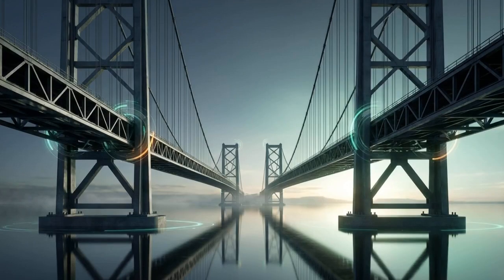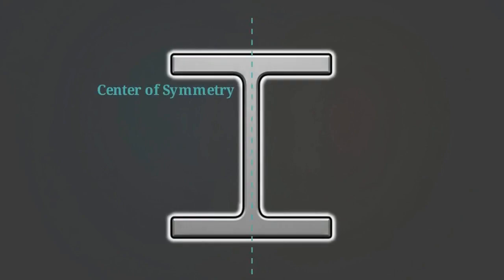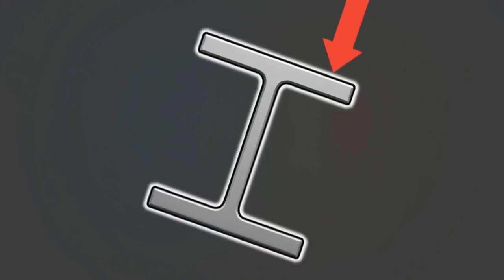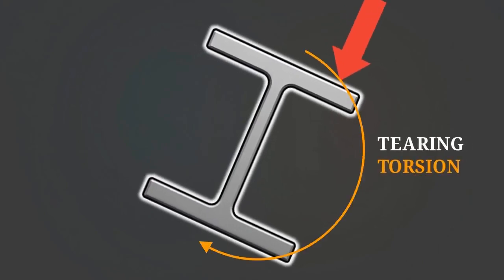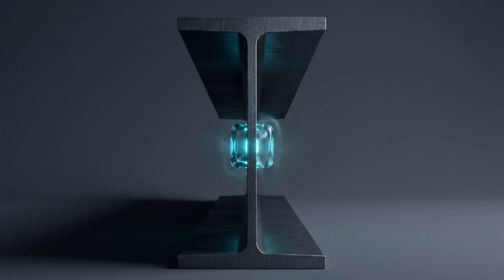But this perfection assumes the load hits the beam exactly on center. If a force lands even slightly off-axis, it introduces a tearing torsion. Finding the single point that can stop that twist requires locating the elusive shear center.